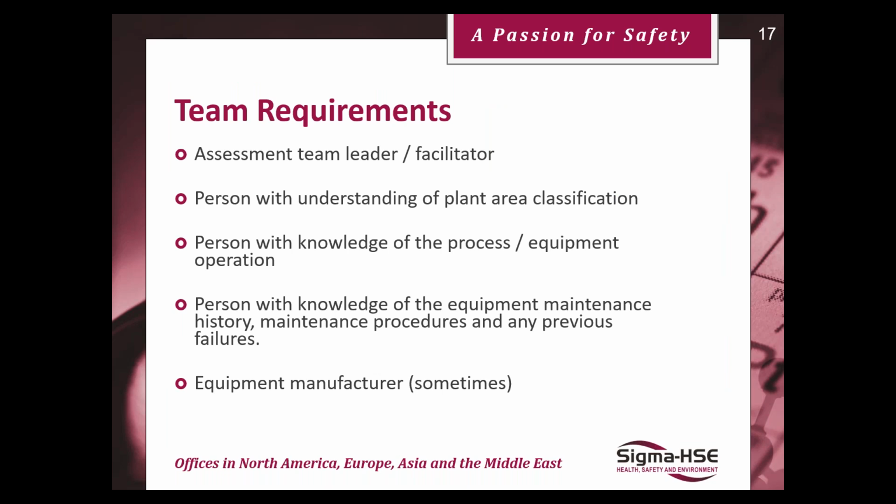So when you go on site and you have to look at the equipment, you usually have a team requirement. The assessment team: the lead facilitator, a person with understanding of the plant area classification. You may need the equipment manufacturer sometimes, because the manufacturer has access to intimate knowledge. Maybe they know the materials of construction, if some things are not stated in the equipment manual. Again, you need a person with knowledge of the equipment, history from experience, the maintenance procedure, and any previous failures.